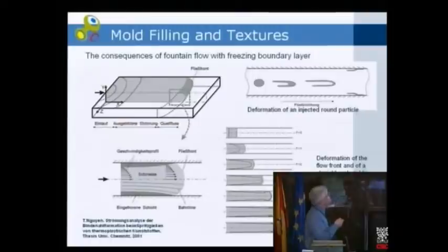When we are filling such a plate by injection molding, we can see here the flow front, which runs through the mold while the mold is filled. And you can see here that the material, the flow lines, are drawn to the outside. And this is a more extreme sample. We have here a volume element, two planes, and during the mold filling, something very interesting happens. The material which is below this volume element, it surpasses the volume element if it's in the middle, and this fraction of the material here, this is the content of this flow element.